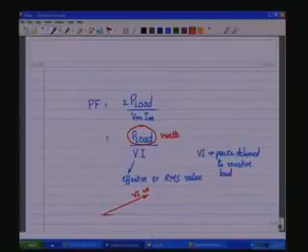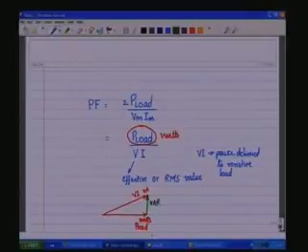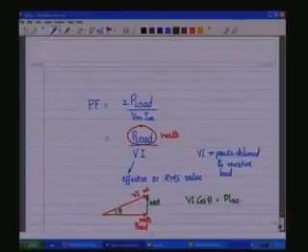So, watts or P load in terms of the phasor diagram, and the vectorial difference of P load with respect to the VA apparent power, this would be the VAR or the reactive power, and this angle theta is the power factor angle. So, V I cos theta will give you P load,